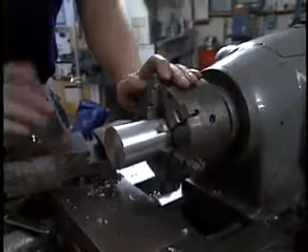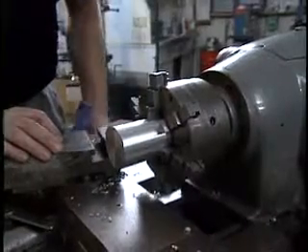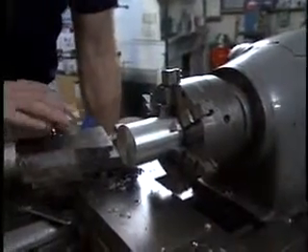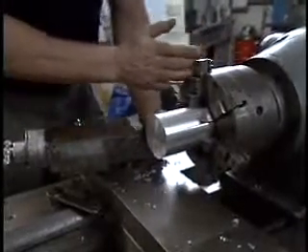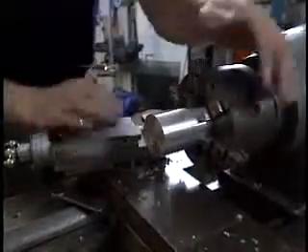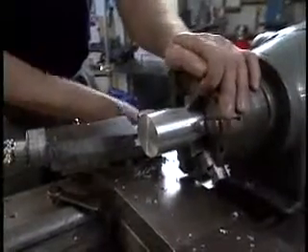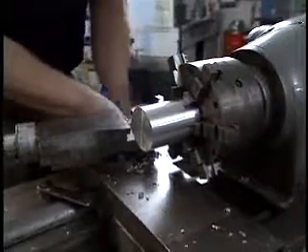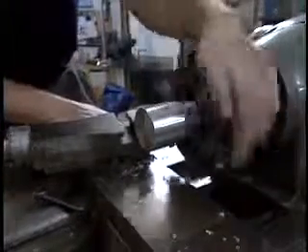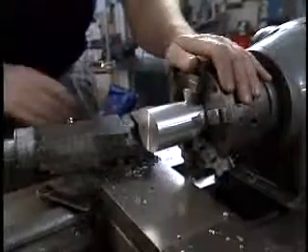In particular, this is very important when you're drilling, because often when you're drilling, you have the compound down very near the chuck. Make sure that you avoid this sort of interference between the jaws, the chuck, and parts of the lathe. Now it's safe to turn the machine on.